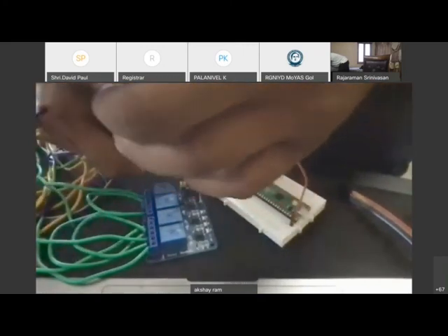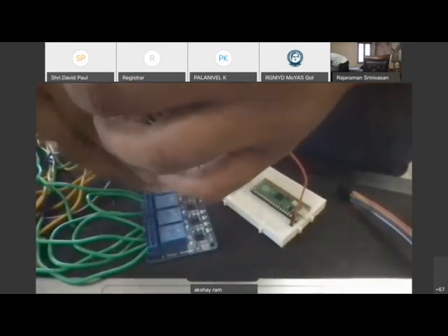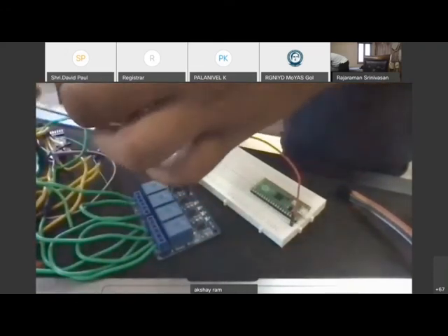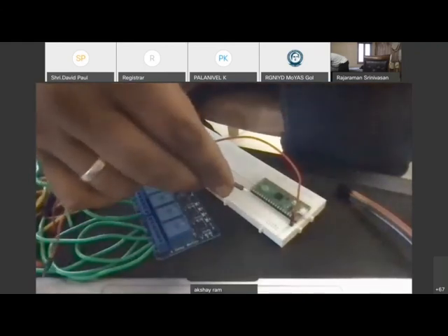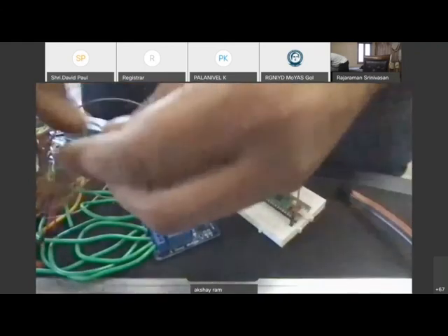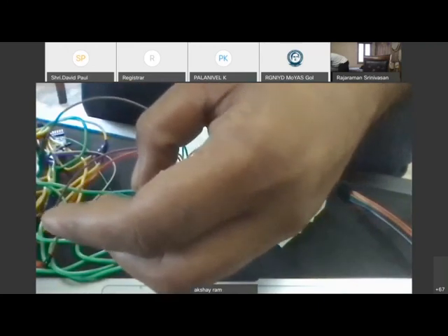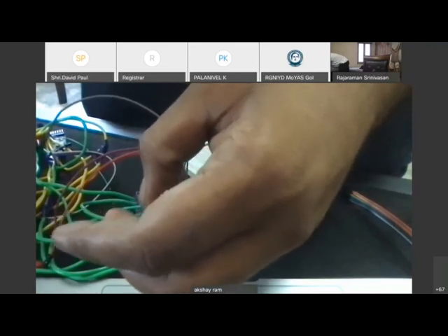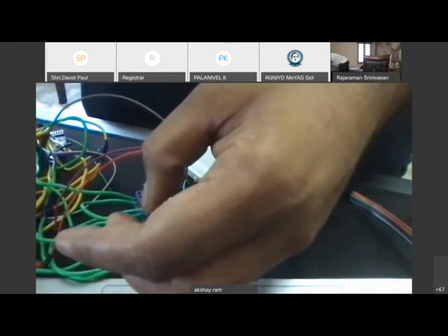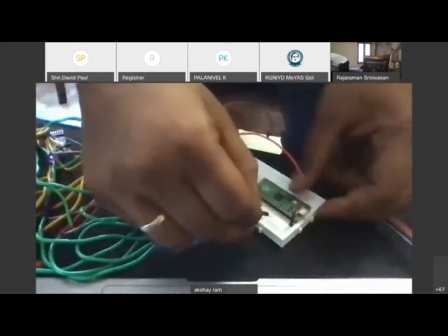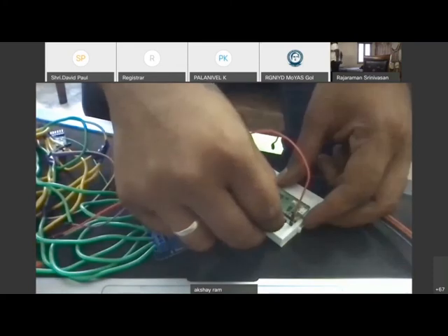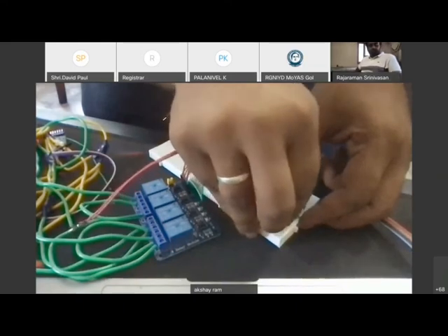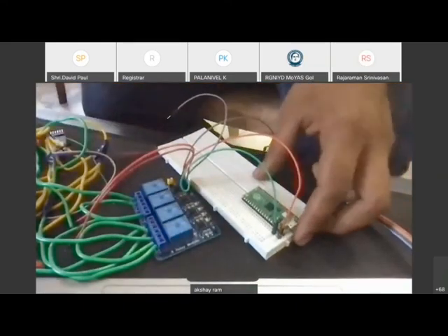So next one, first we have connected the power. Now we will have to earth it. So the ground we will give it to, I think, the third one. Third or second? Third one. One moment. Let's check the drawing. Yeah, third one is earth. So 1, 2, 3. So now it has power. Now it's also earthed.